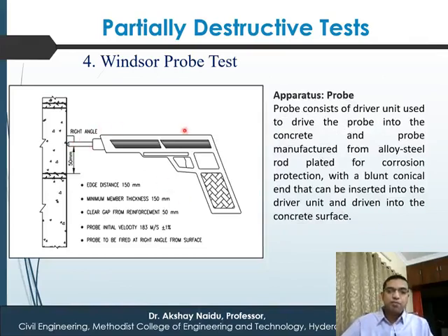So Windsor probe, it is like this gun, and this is the Windsor probe. You shoot and this probe gets driven into the concrete with a force. So this probe is manufactured from alloy, steel alloy, plated for corrosion protection with a blunt conical end.